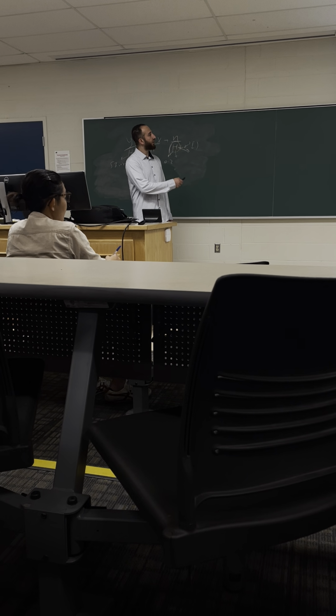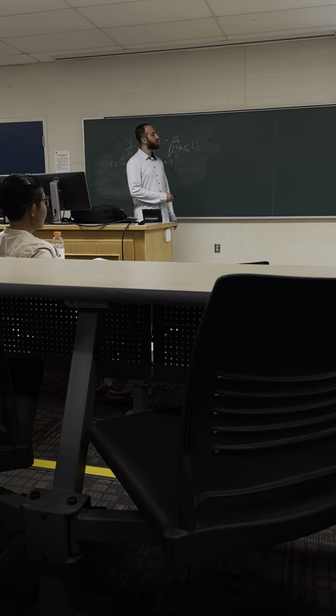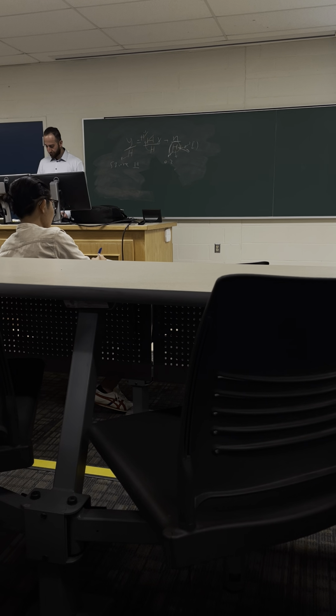If you need to find the minimum mean square error, you prepare the rule. You find H transpose H plus sigma square, where sigma square is 0.5, multiplied by the identity matrix, and then you obtain this value. Then you can obtain the weight matrix of the minimum mean square error, multiply it by y, the received signal, and then you obtain the x of the minimum mean square error.